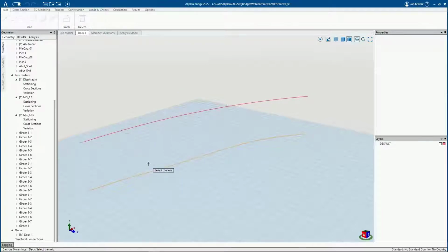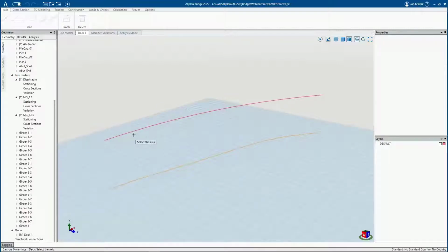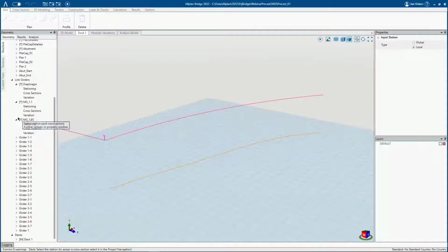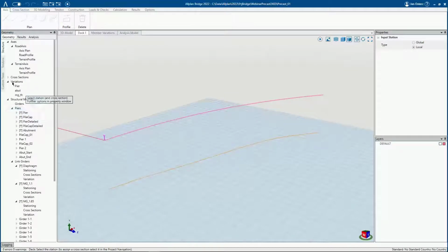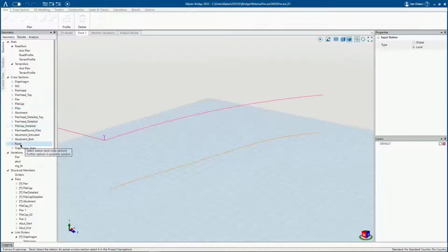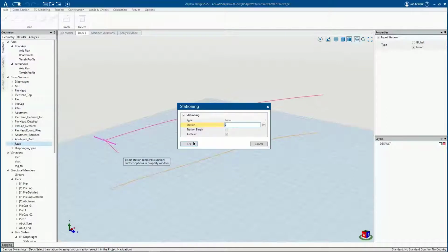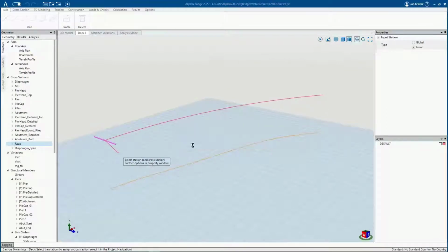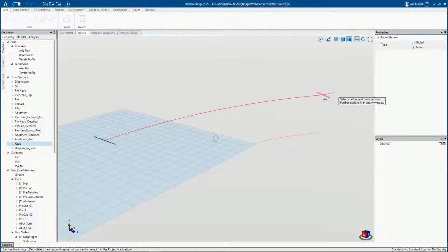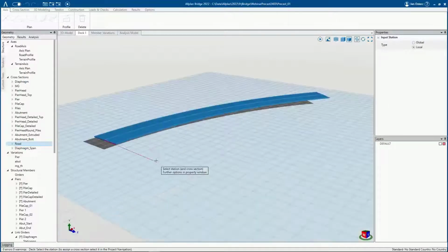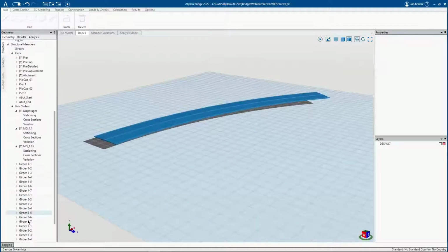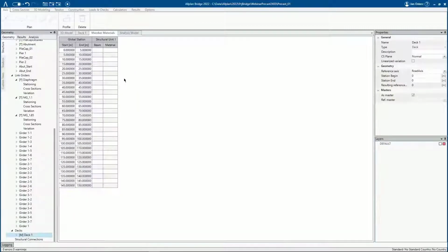For this, you can see I have this empty space now with both axes, and here I can define my road structure, or let's say my deck structure. I will select the axis, and I will choose the appropriate cross section, which is road, and I will just drag it, or by this I mean extrude it through the whole length, like this. Okay, and now I will just assign the material, and then I will position it on the final 3D element.